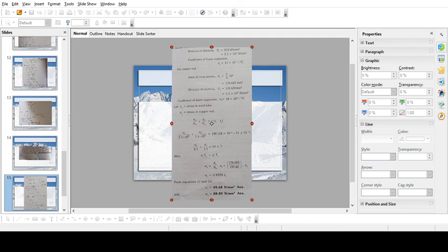It is not t, it is a mistake given; it is As. So sigma s As should be equal to sigma c Ac. Now sigma s equals Ac by As into sigma c. Small ac is not there, it is simply sigma c.